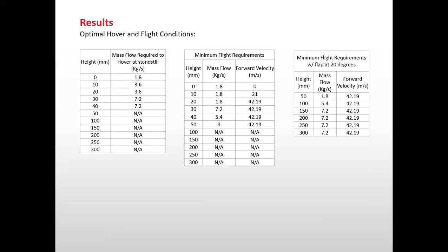Based on all CFD simulations, we have identified some minimum flow requirements to generate 890 newtons of lift. Our simulations show that above 50 millimeters, the airfoil is out of ground effect and experiences dramatic losses in lift. The reworked flap design can operate outside of ground effect, however.